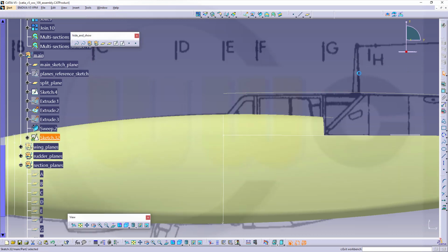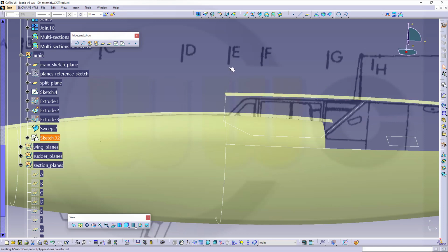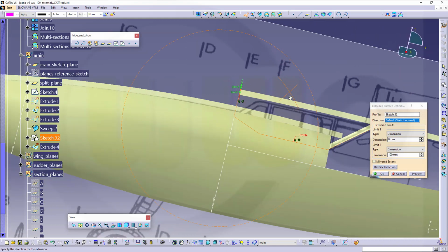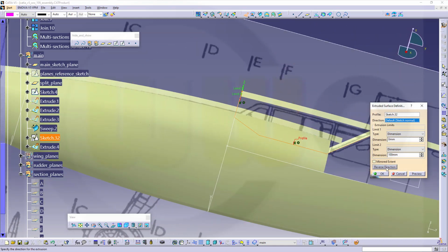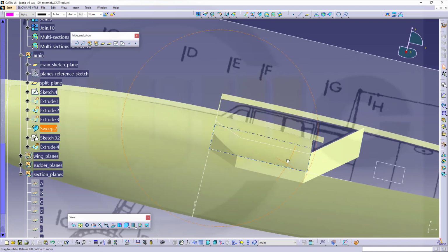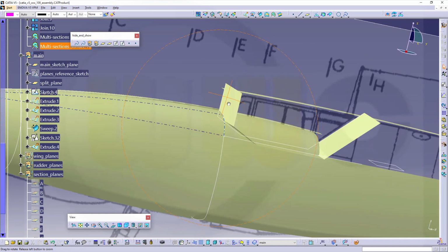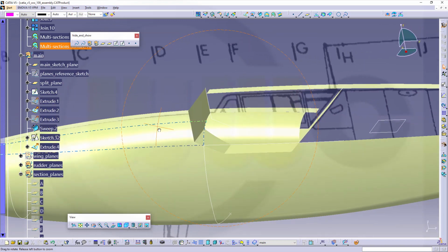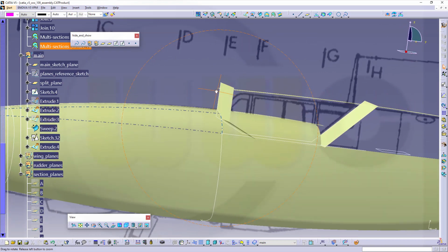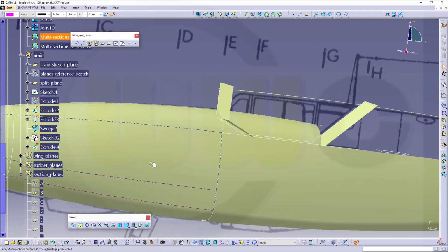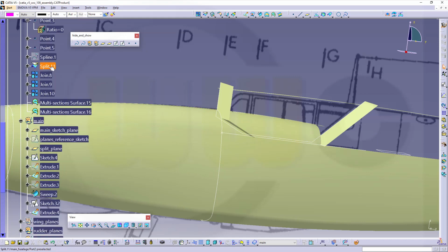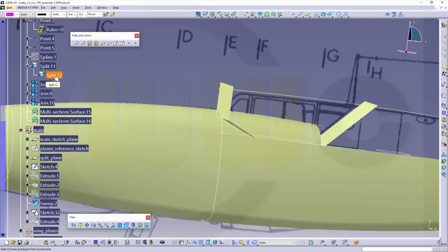Now leave that sketch and make an extrude with that sketch right now. So go for an extrude. Yes, in the other direction. So reverse it and make it maybe 550. Yeah. And now I want to split the surfaces, but I need to bring back this one, and that was a split. Maybe that split.